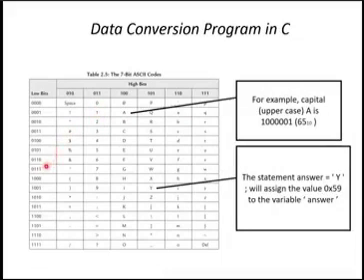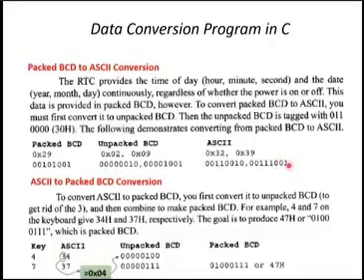So you can see here we have two characters in the form of hexadecimal. So we need to separate. This one contains 4 bit. This one contains 4 bit. So you need to separate. The new unpacked representation of the packed BCD is 02 and also 09.